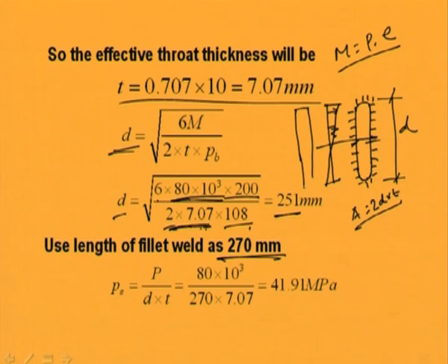Shear stress will be developing, Ps, and the maximum stress at the extreme fiber will be square root of Ps square plus Pb square. So the length has been decided from Pb. If Pb is becoming around 108, then length can be decided. But if we put the same length, then the resultant of these two will become more than 108, because Pb has been considered as 108.